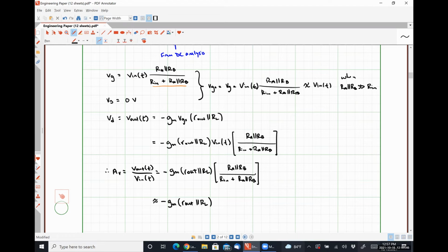So we see here that our overall voltage gain for this system is dependent on a parallel combination of resistances. So what's something else that we need to do to maximize our output? When we have two resistors in parallel, that equivalent resistance is smaller than the smallest resistance. So having those two in parallel makes this amplify signals worse than if we only had one of the resistors.